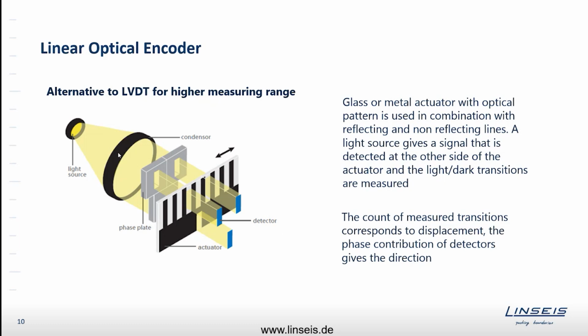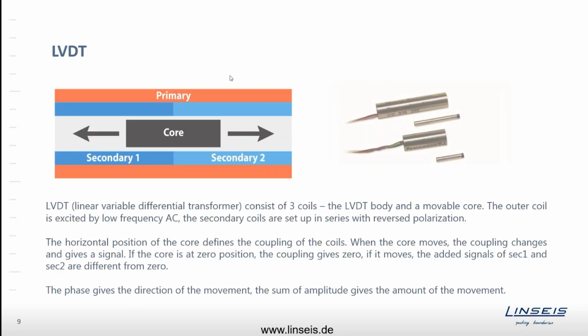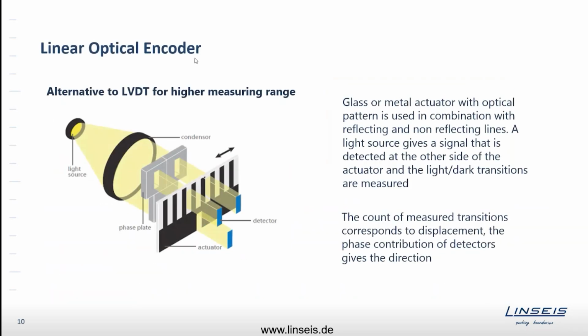And then you have to clean the system. Therefore, you need special tools. You need to send it to the manufacturer. You need to clean it in a clean room, maybe. That's cost intensive, and that's not user friendly. That's why we usually focus on using LVDTs. However, if somebody wants an optical encoder system as a standalone detection system, they are available on the market, so you can just purchase one. So we can offer a system using an optical encoder as well. However, just keep in mind that maintenance may be an issue here. That's what you need to know.